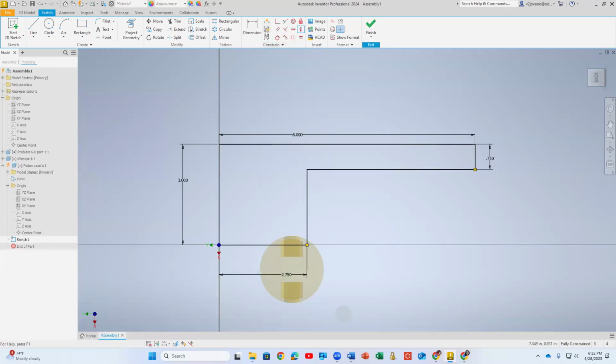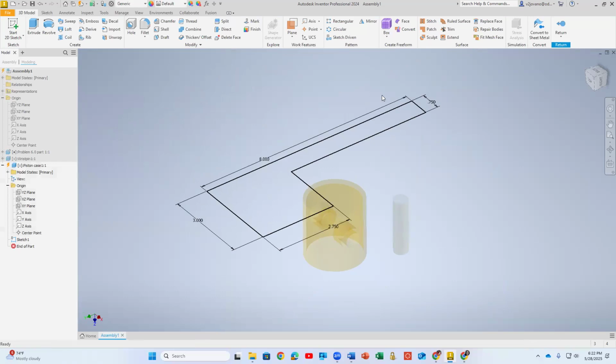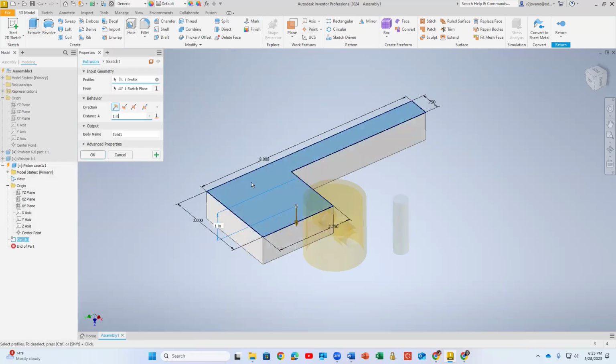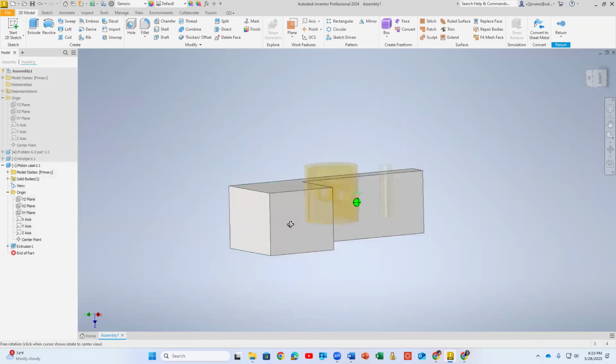And if I want to show my constraints, I will just select everything, and you see all things are there. It's a fully constrained sketch. So I really encourage you to create fully constrained sketches. It's easier for editing. And now they want us to extrude this by 2.25. And don't worry if yours is not oriented the same way, it really doesn't matter.